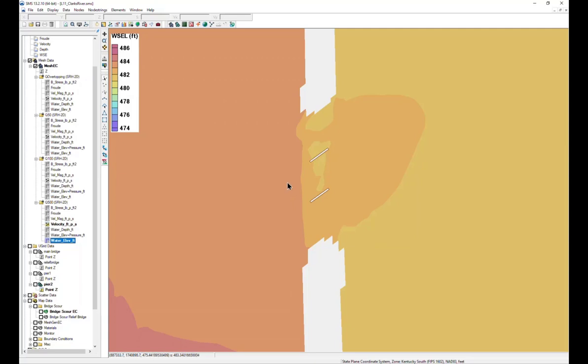We'll use that water surface elevation relative to the average channel invert at the face of the bridge to compute the approach depth. And then the opening at the bridge face would be the average low chord at the bridge minus the average channel bed elevation. And so those are the two main things from the results that we need to export from the solution manually, as well as the bridge deck thickness.